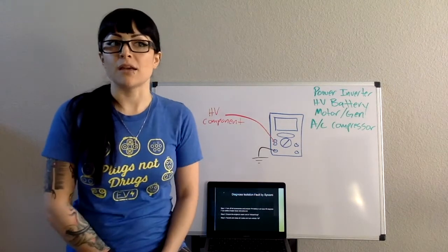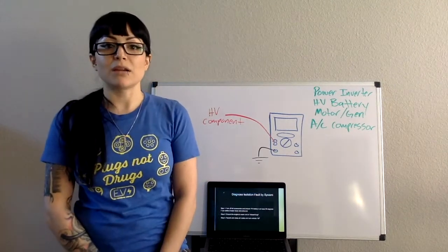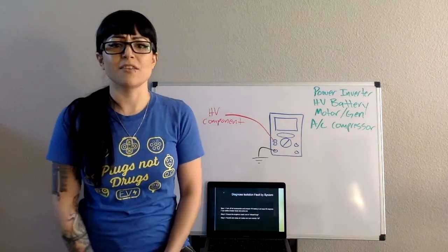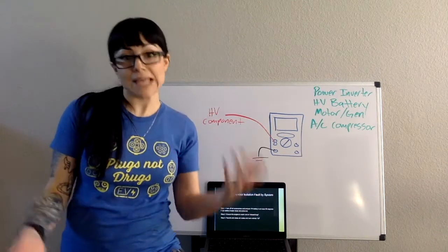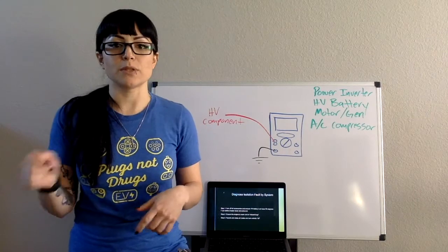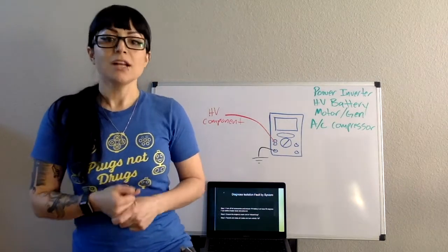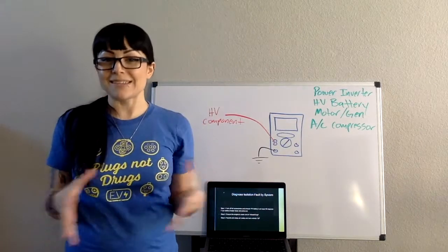Kind of like on a parasitic draw test, right? Where you hook your meter up, you see an excessive amperage draw, and you just pull fuses until the meter drops, right? Kind of the same process, except instead of pulling fuses, we're going to be turning systems on and off. So follow through with me here. First thing you need to do is sort of reset everything, right?